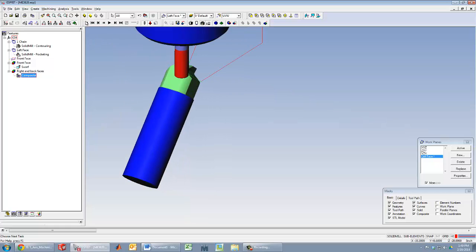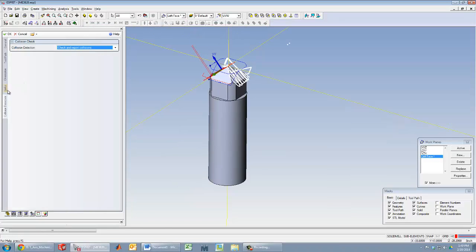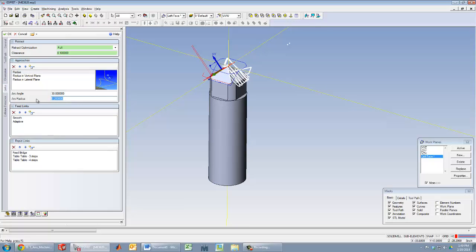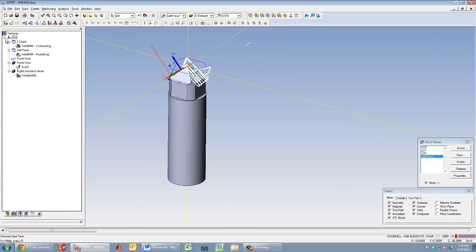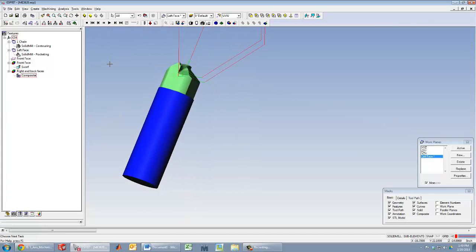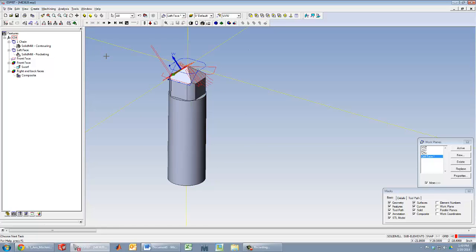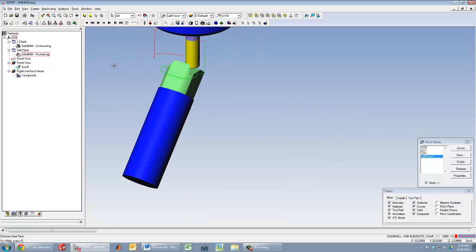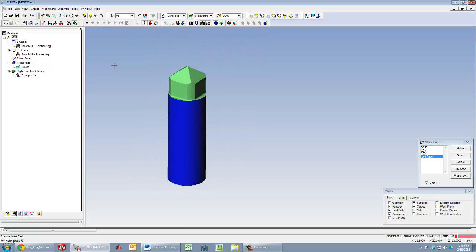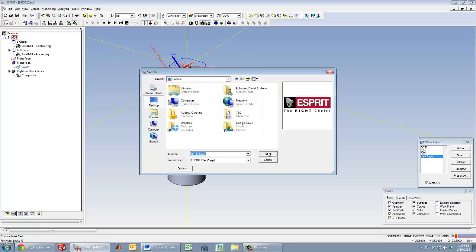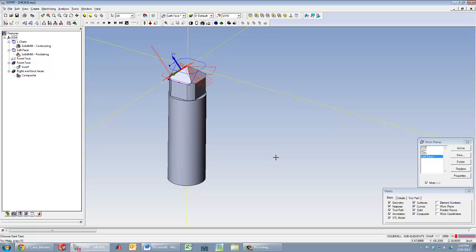And we're crashing. That looks like we're crashing on the transition. So let's go look at our approaches, radius. Let's make that 1/2 inch, see what that does. And we appear to be fine. Okay, so go ahead, stop that. Save the entire thing. Simulate the entire thing. Now you can save the entire thing. And that's your lab. Now go ahead and machine it.